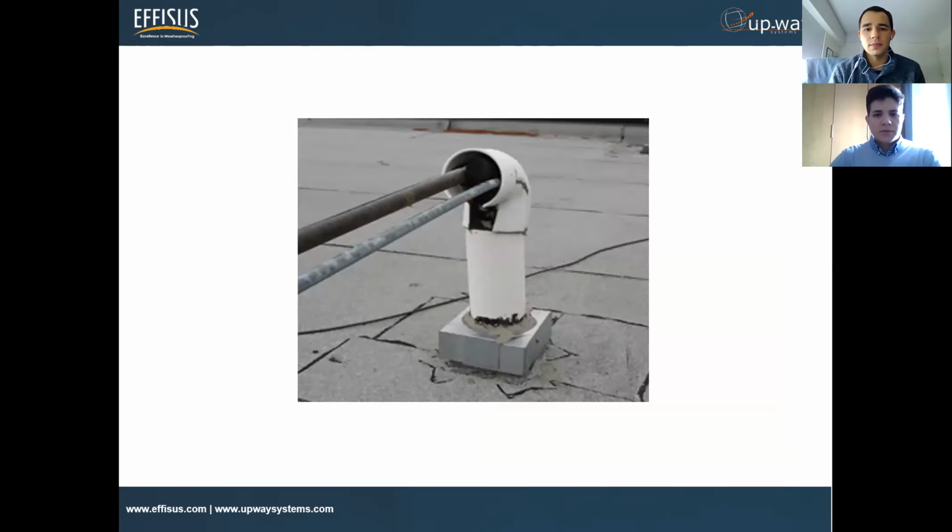Yes. So this is another very common thing here. It would happen since you have this type of penetration coming through, and even this cable coming through the inside. So even a heavier movement is expected here, and even the roof itself starts cracking all around the penetration. And you see this and think, oh, this is not common, this will not actually happen. But we see this many times on sites, correct, Ricardo? Yes, without a doubt, João.